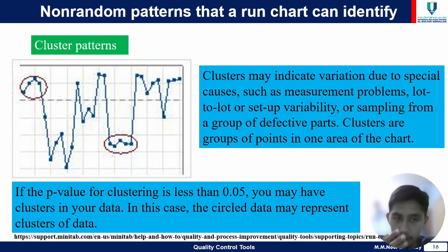Secondly is the cluster pattern. Clusters may indicate variation due to special causes, such as measurement problems, lot-to-lot or setup variability, or sampling from a group of defective parts. Clusters are groups of points in an area of the chart.